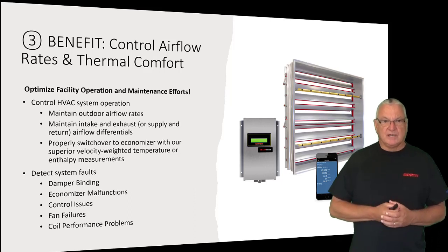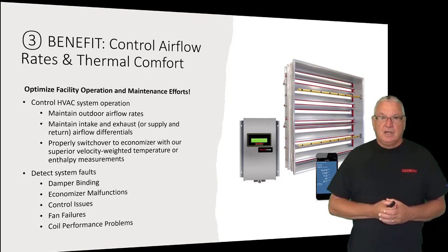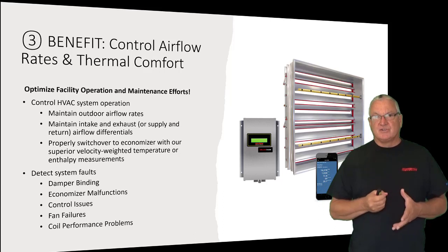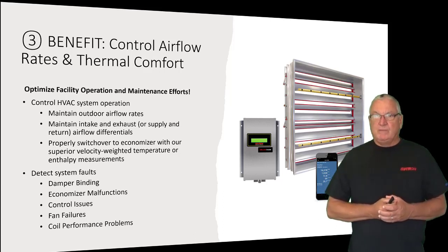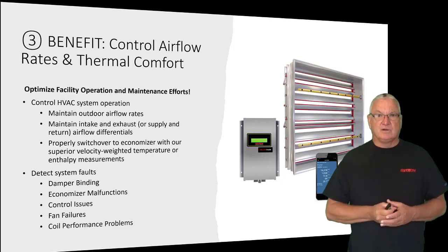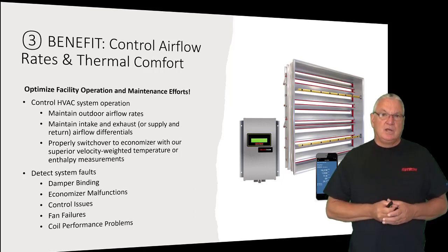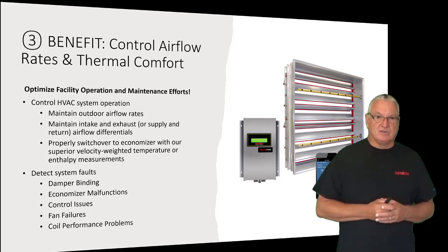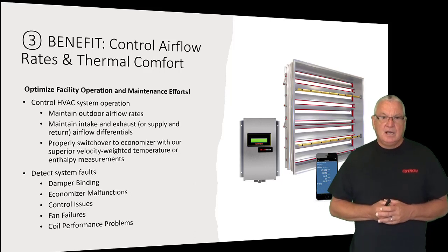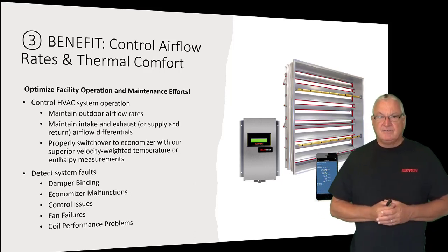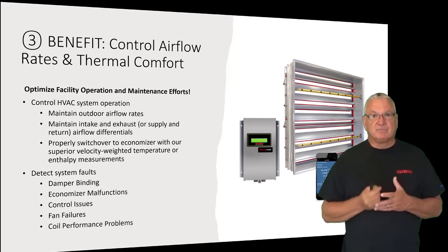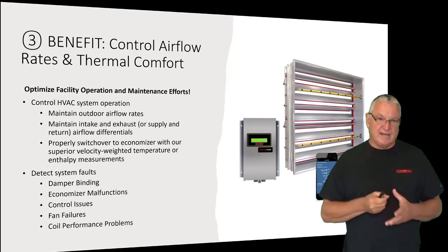Also for the control airflow rates and thermal comfort, we really want to get into specific control strategies. Basically, we believe in all airflow control strategies. That means we're going to control outdoor air for dilution. We're going to control differential flow rates, or the difference between supply and exhaust flow rates, for pressurization. We want to make sure that we have the instrumentation in place if you have an airside economizer for proper switchover there. So we're going to get into that.